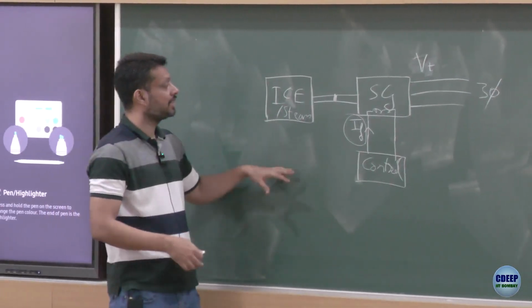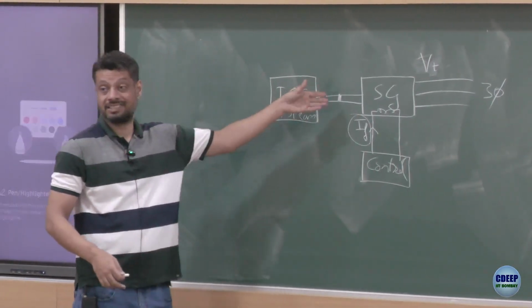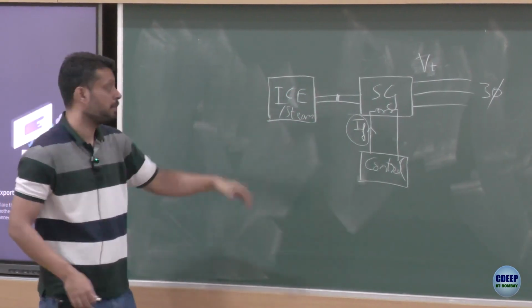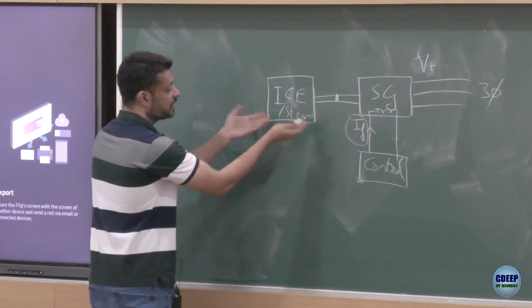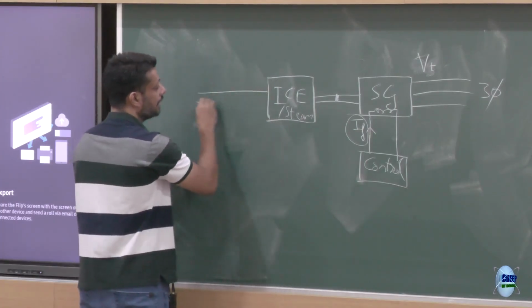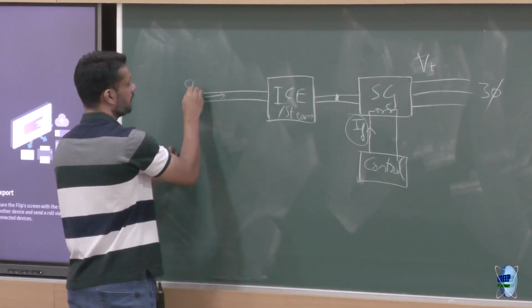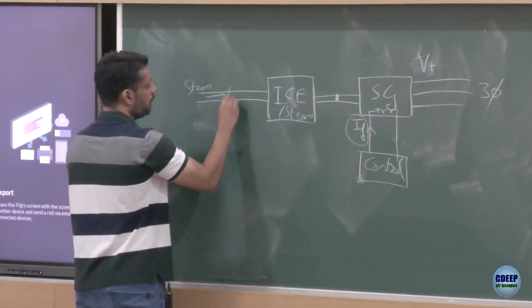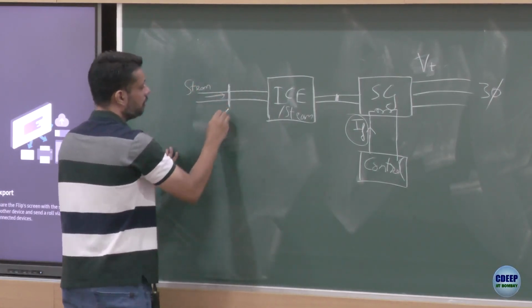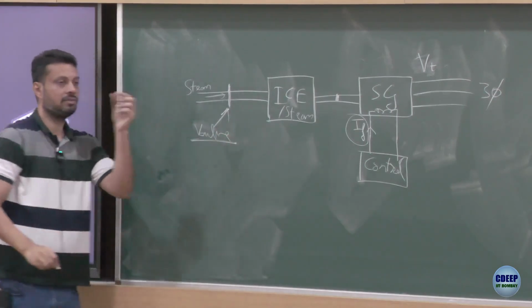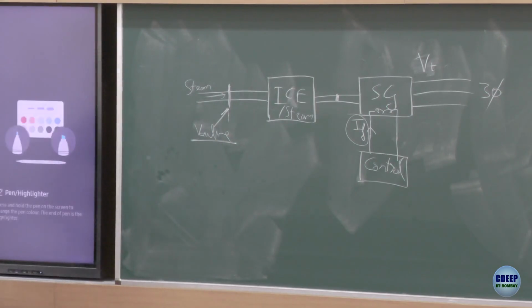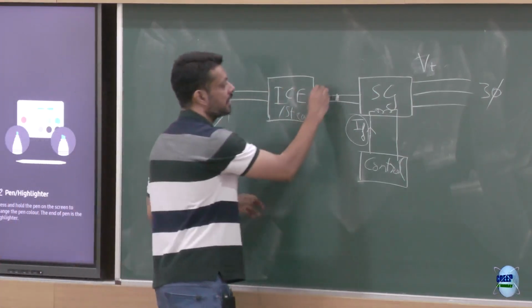The other thing that is controllable is, directly you cannot touch the speed, the shaft is moving at very high speed, but the input to this, right. For example, what can be input to this? If it's a steam turbine, then it could be getting some form of steam, and there may be a valve, right. You can adjust the valve opening and that would lead to more steam or lesser steam. If there is more steam, more pressure, this guy may rotate faster.